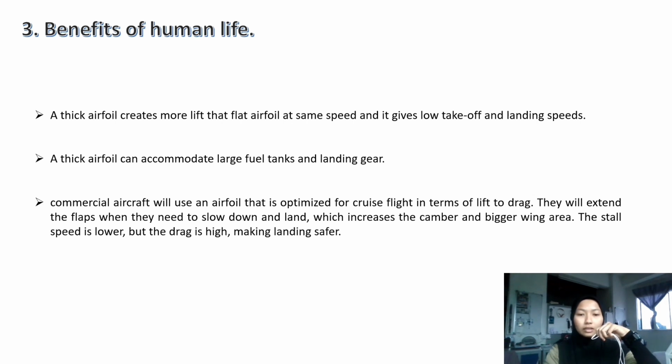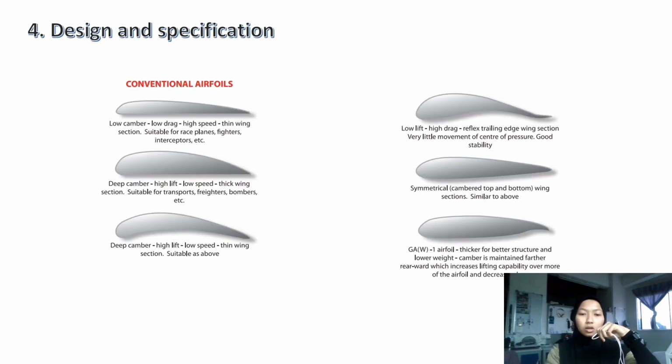They will extend the flaps when they need to slow down and land, which increases the camber and gives a bigger wing area. The stall speed is lower, but the drag is high, making landing safer. The design of airfoils is basically based on the function of the aircraft.